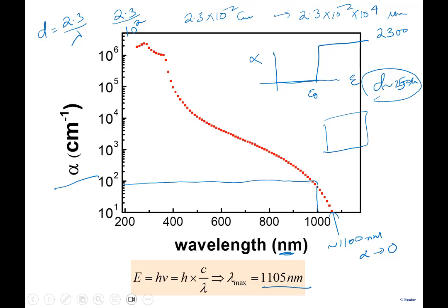You can determine what fraction of the photons are going to be absorbed. So you see there's a problem with silicon: for longer wavelengths, the absorption coefficient is pretty low. Even here, it is coming to be 230 micron, right?